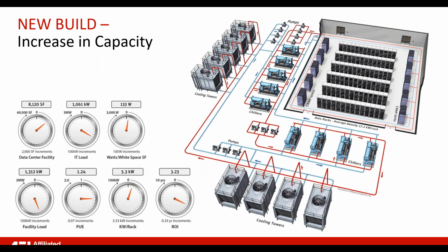What happens if we want to increase the capacity of our baseline new build scenario? We're looking at potentially increasing the square footage and increasing IT load. We went from about 500 kW to now a megawatt. Obviously our facility load has increased, our PUE may have stayed about the same, and the density per rack has stayed about the same. We're seeing an ROI for this type of application maybe in the 3 to 4 year range. Next slide.